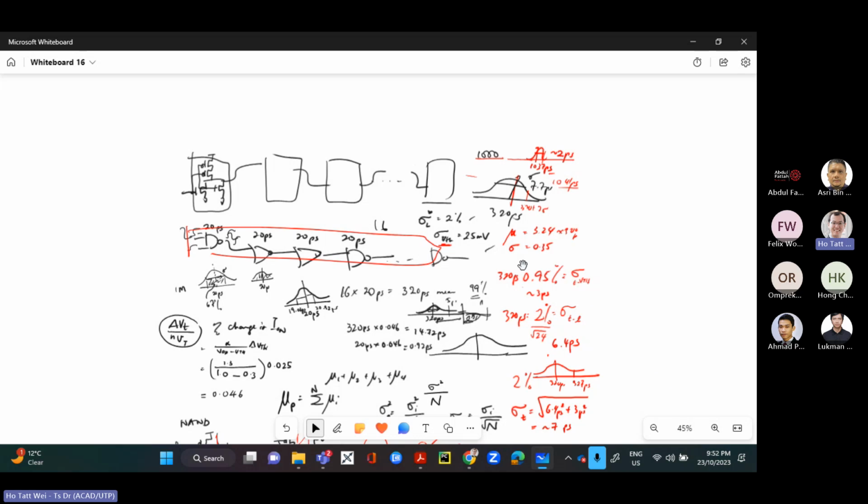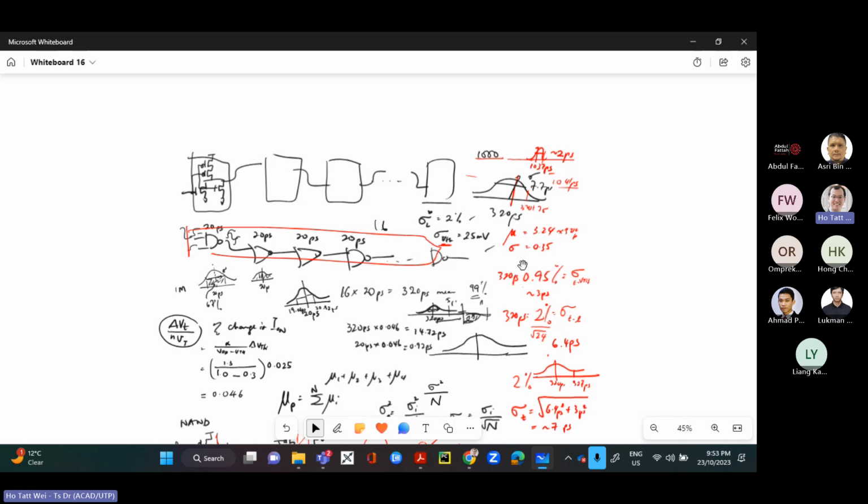Because the standard deviation, the argument that you can use is that the lithography tools are usually made by two or three companies in the world only. Mostly it's the same lithographic tools, so they probably achieve the same performance. There may be slight differences in the actual value of the standard deviation, but it's not going to vary by too much. It'll be a good estimate if you can look up in the literature the typical process variation values like threshold voltage variance, line edge roughness variance, oxide thickness variation. Right? So that'll be good for you to know, keep it handy, and to track as new processes are released.